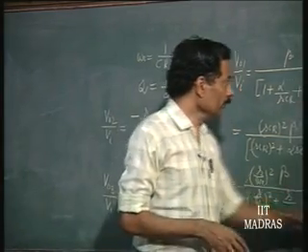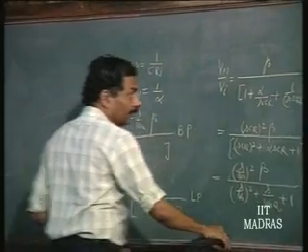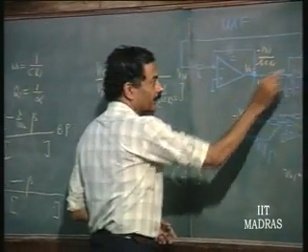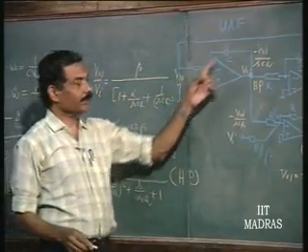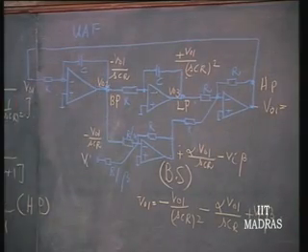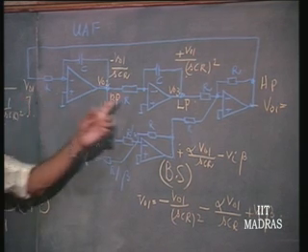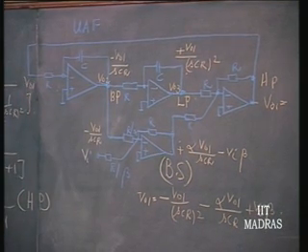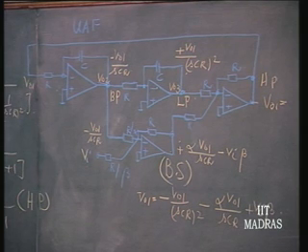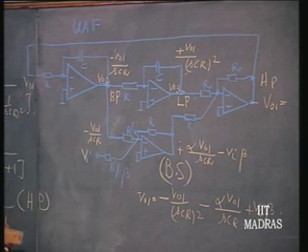So, we can do this very simply by replacing this integrator and this integrator, because here RC time constant means the 1 over frequency, omega is equal to 1 over RC. So, if I make both these resistances depend upon a voltage, that means if this is made voltage controlled, or if I put a multiplier here, it becomes a voltage controlled filter, right.